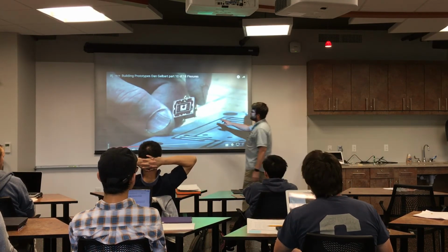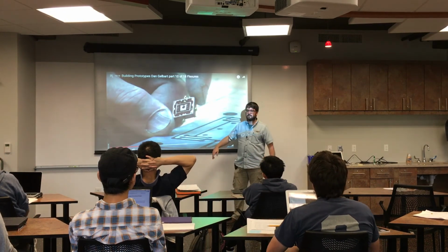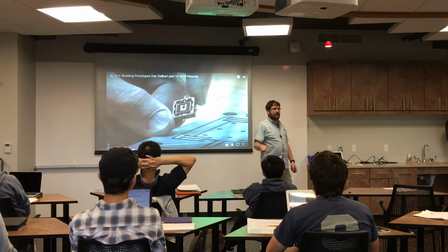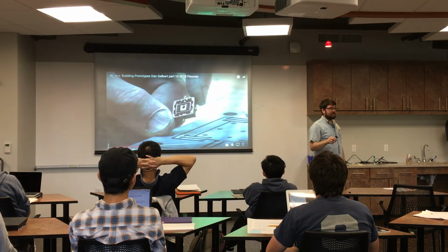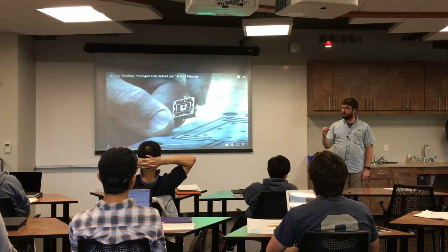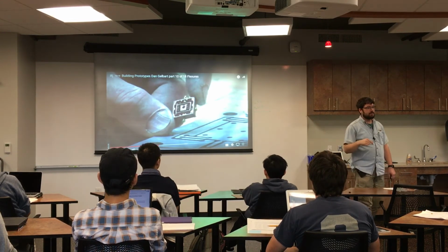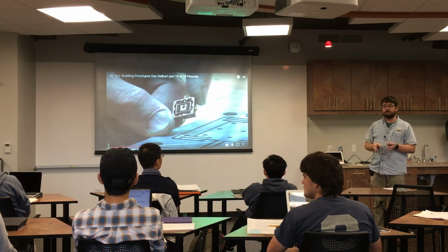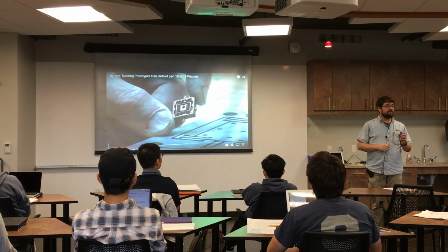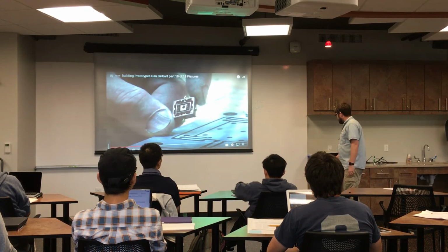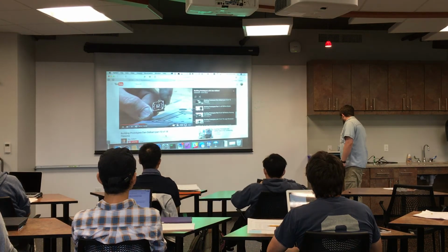We won't go on, but you should definitely go watch some more of his videos, or watch the rest of this one. But this is actually a 3-axis positioner that's cut out of a material with a very low thermal expansion coefficient. And he talked about Invar, which is one material that, if you need anything that's not very thermally dependent, you should cut it out of Invar. It's a metal with very, very low thermal expansion. It's also very expensive and very hard to machine, so make sure that's really what you need before you do it.